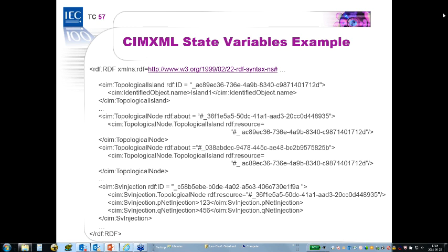Plus, you'll notice down here, there are 4 boundaries that are sort of one-sided. For example, Central has an east-central boundary, but no East on the other side of it. Other bilateral boundaries are complete because they have representations on both sides. To complete the case, for each one of the boundaries that only has one side, you need to develop what's called an edge model. And the simplest form of an edge model, and this goes back to the question on equivalence that Larzola was answering, the simplest way to create an edge model is just an equivalent generator stuck onto the tie lines. And for that kind of an equivalent, you can automate the process completely.